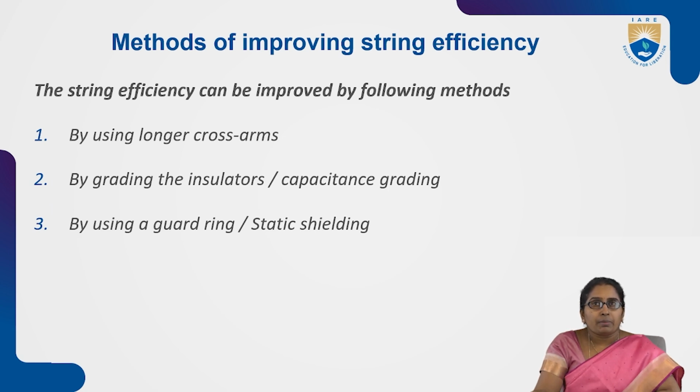Suspension type insulator means, as the name itself suggests, a number of porcelain discs are connected in series by metal links to form a string. Here we know that there is a non-uniform voltage distribution over that string.